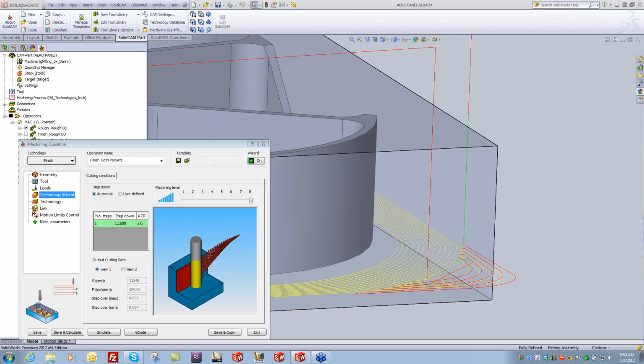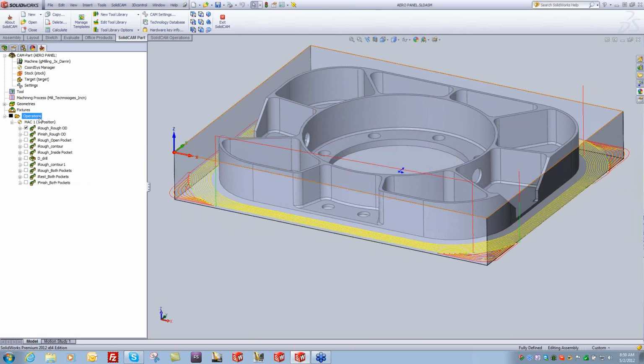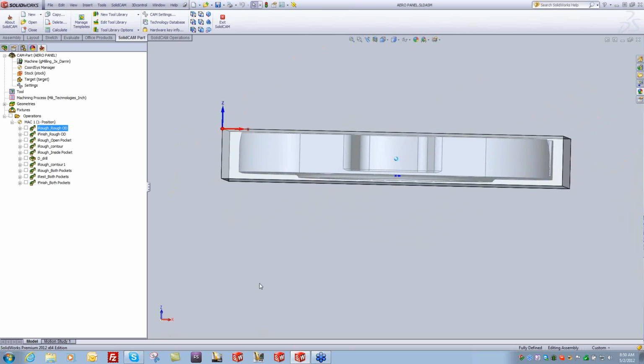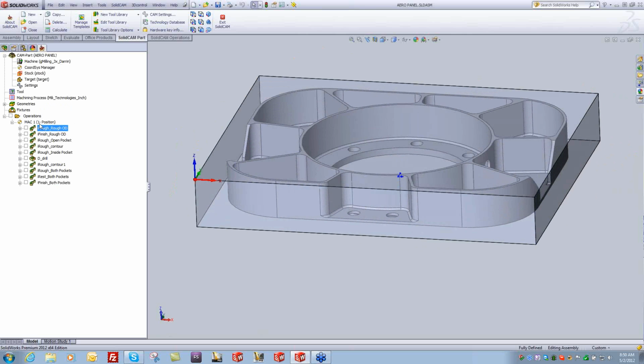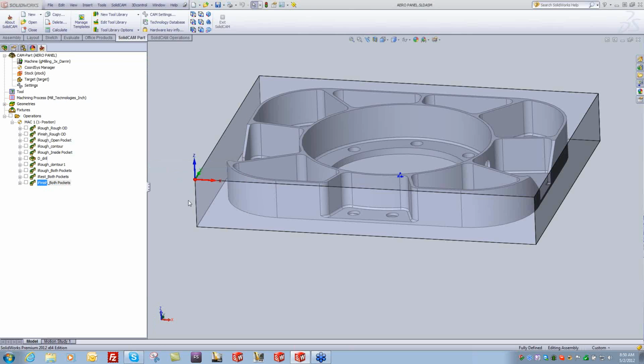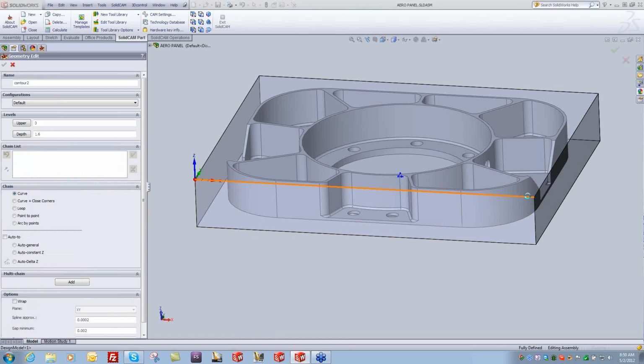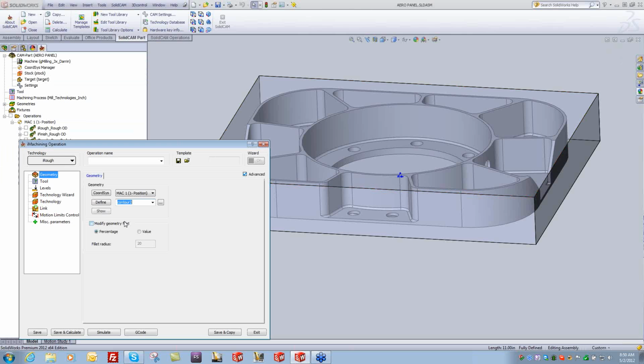Okay. That actually brings up another good question. Let me illustrate both face milling and the materials a second time here, because we didn't go over creating a material, and that is kind of important. So what we'll do, iMachining face is very easy. If we're going to cut this face, top of this part here, in fact, is this? Yeah, see the material's up a little bit, so yeah, we have some face to cut off. So I'm going to go ahead and create another iMachining operation real quick. For the facing, I'm going to simply grab this outside edge because I want to face the whole stock off, right? So we'll go ahead and grab that.